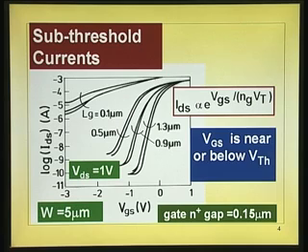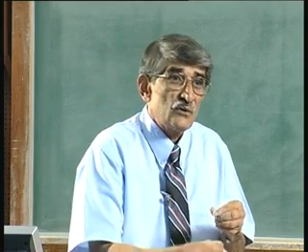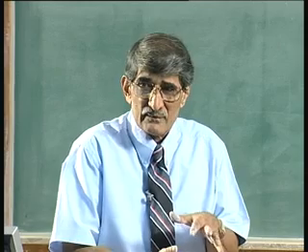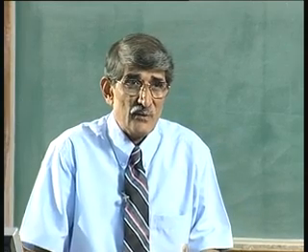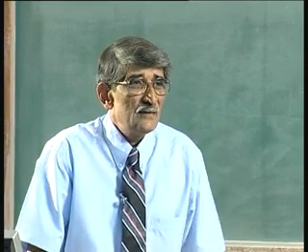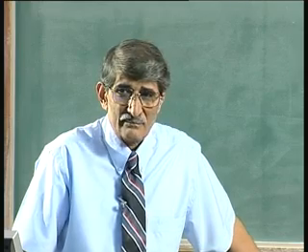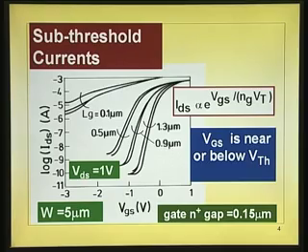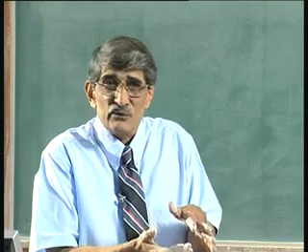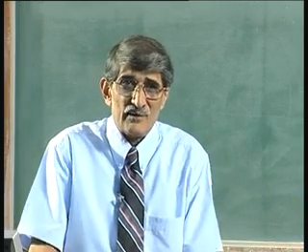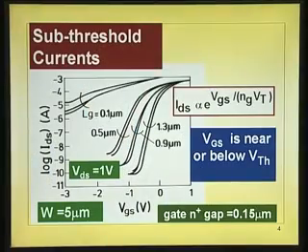So, what we are telling is, when you go to shorter channel lengths, the potential barrier at the source end to the transport of electrons towards the drain end keeps on reducing, or it is controlled by the drain also. For a given drain voltage you will have that factor N g greater than 1, and if you increase the V d, that barrier will further reduce. You will have another factor coming due to that V d, but I am not talking about that. I just want to point out that the two dimensional effect harms the performance of the device.